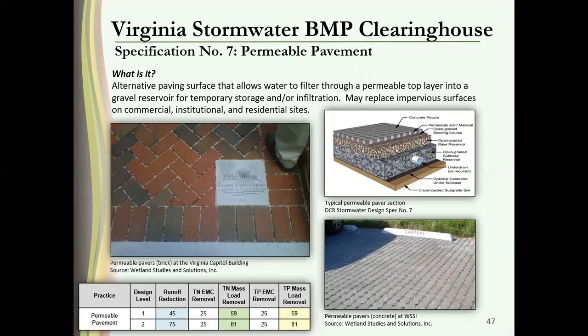Permeable pavement. This to me is the other no-brainer besides the roof. What do we have a lot of that's impervious? Roadways, things that we drive on. So in certain circumstances, depending on the kind of vehicle loading or the vehicle frequency, the kind of traffic we're looking at, it may be possible to replace that impervious surface with a pervious option. And there are lots of pervious pavement options these days.